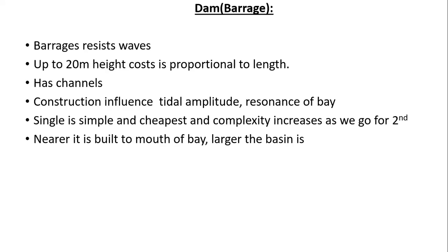The precise design of the barrage and its mode of operation will depend critically on the requirement of power, and these have to be carefully analyzed for the economics also. The simplest and cheapest schemes are single barrage designs. These trap the water in the basin at high tide to generate on the ebb. Ebb means the flow back of waters.